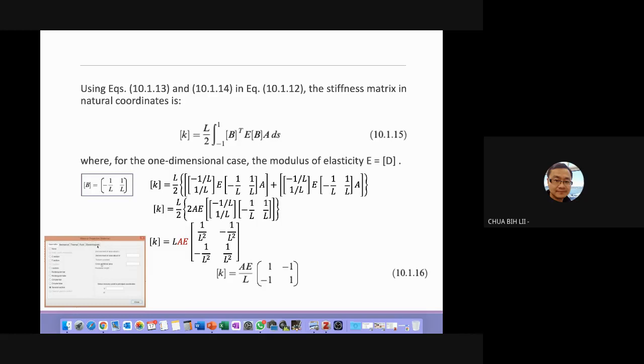When you define the material property for your bar element, or for the line element itself, they may provide this blank empty space for you. So you may need to define what is the cross-sectional area, in order for the analysis result to be meaningful.